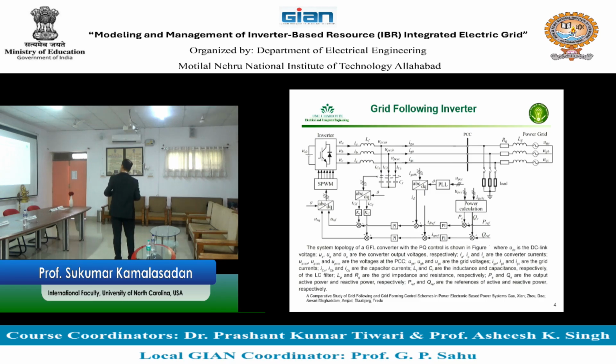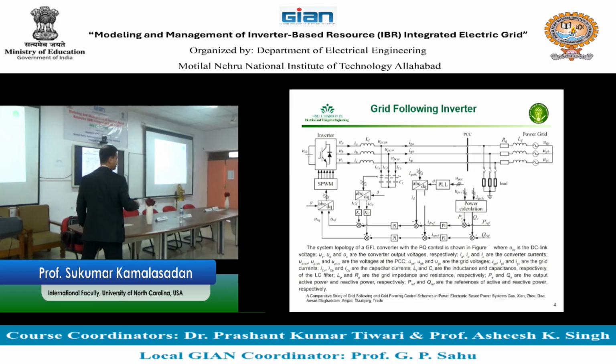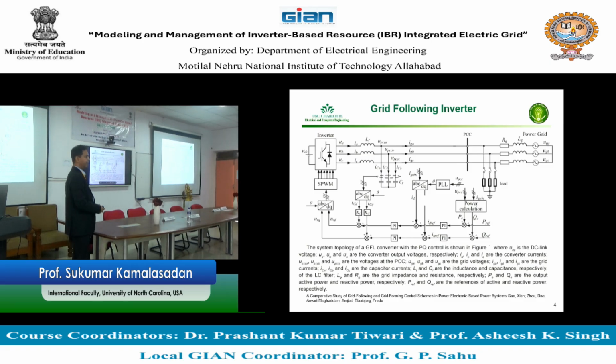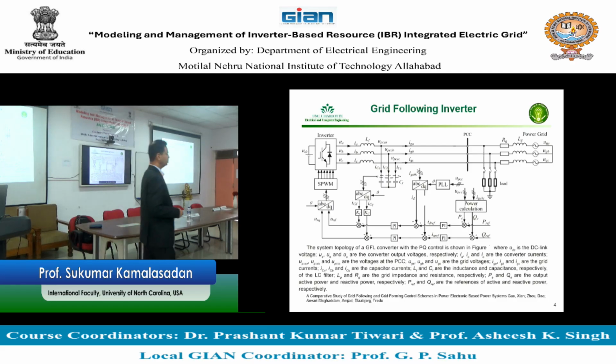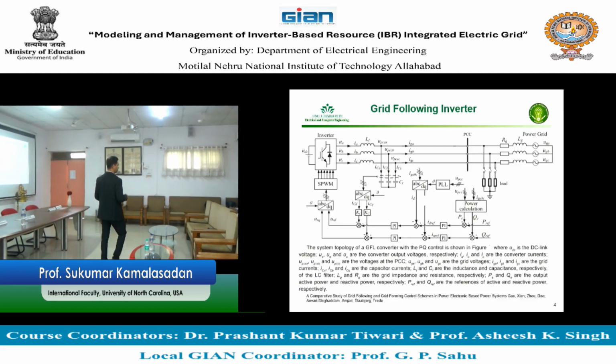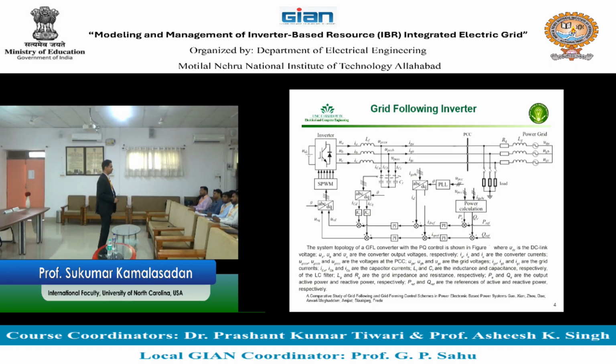So that voltage change happens, it changes the pulses, and then the output changes, and then the output passes through a filter. In this case, it is an L inductor and a capacitor, an LC. So that filter is called an LC type of filter. Is that the only way you connect a filter? No, you can connect the filter just as an L, just an inductor. You can also connect the filter as LCL. You can do several different combinations of filters. So that filter is actually not a part of the inverter. The filter is to clean the power output going out from the inverter.